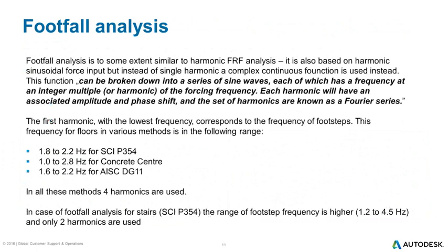Footfall analysis is to some extent similar to harmonic FRF analysis. It is also based on harmonic sinusoidal force input, but in case of footfall analysis, single harmonic components are not used. To model the footfall effect in a way closer to reality, a more complicated continuous function is used, and this function, as it is stated in the code, can be broken down into a series of sine waves, each of which has a frequency at an integer multiple or harmonic of the forcing frequency.